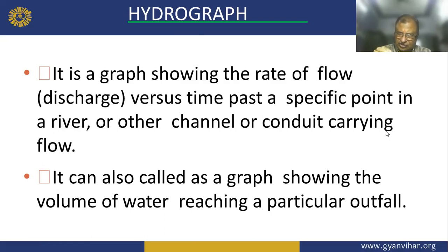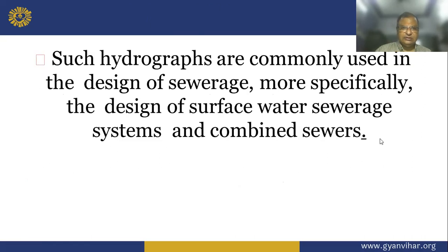It can also be called a graph showing the volume of water reaching a particular point. Such hydrographs are commonly used in the design of sewerage, especially the design of surface water sewerage systems and combined sewers.